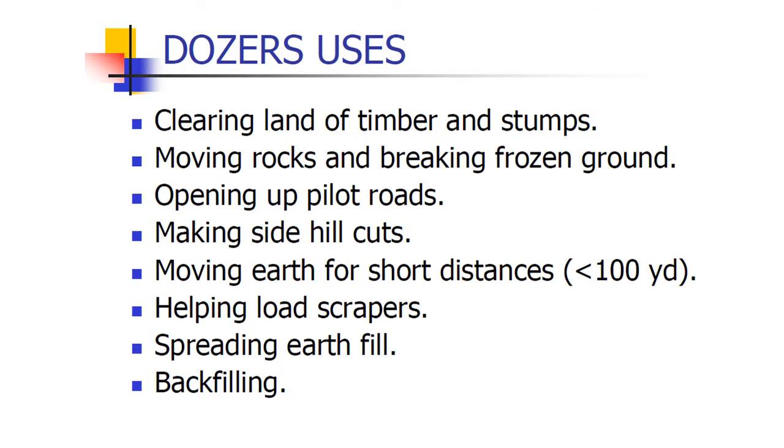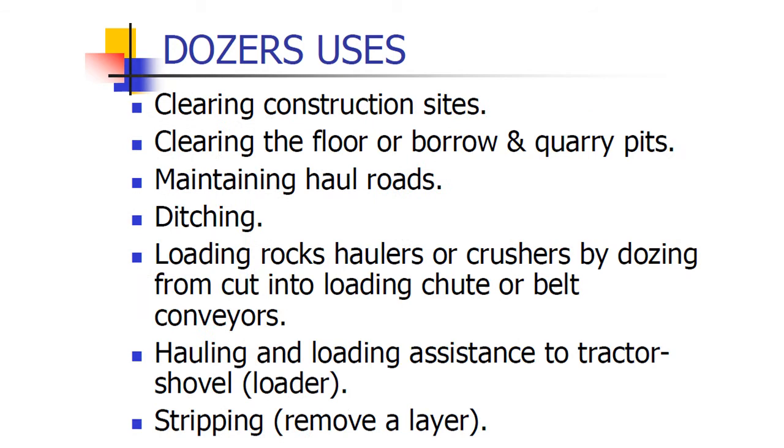In terms of usage, there is a very wide variety, starting from clearing land, moving rocks, opening up pilot roads, making side hill cuts, moving earth for short distances as mentioned before, helping load scrapers, spreading earth fill, clearing construction sites, clearing the floor of borrow or quarry pits, maintaining haul roads, ditching, loading rocks, rock haulers or crushers, hauling and loading assistance to track shovels, tractors or shovels, and stripping, removing the uppermost layer that we have discussed before.